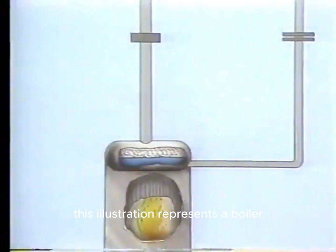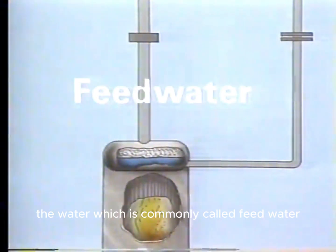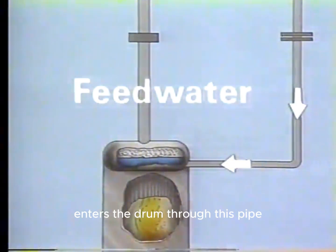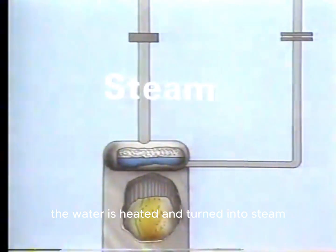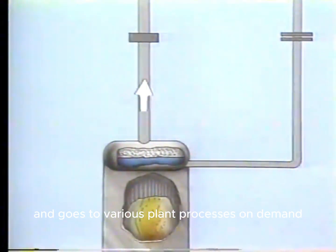This illustration represents a boiler. As we've learned, the heat produced by the combustion of air and fuel in the furnace turns the water into steam. The water, which is commonly called feed water, enters the drum through this pipe. The water is heated and turned into steam. Steam leaves the boiler drum through this pipe and goes to various plant processes on demand.